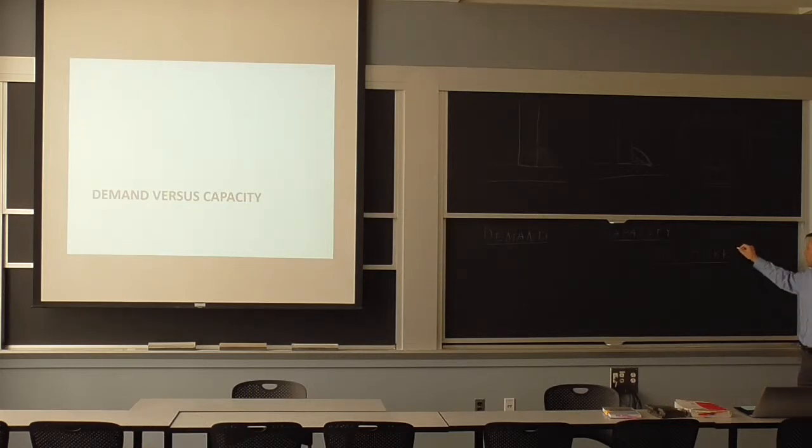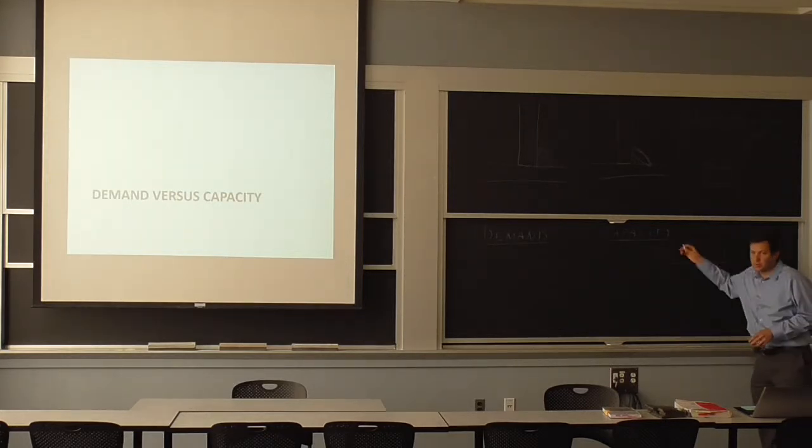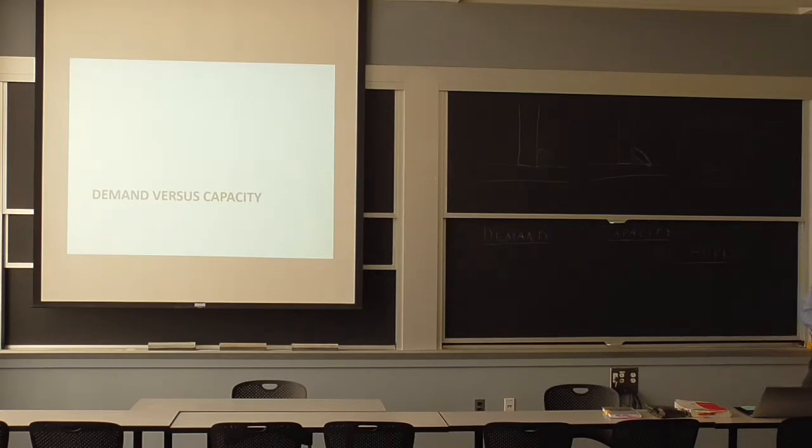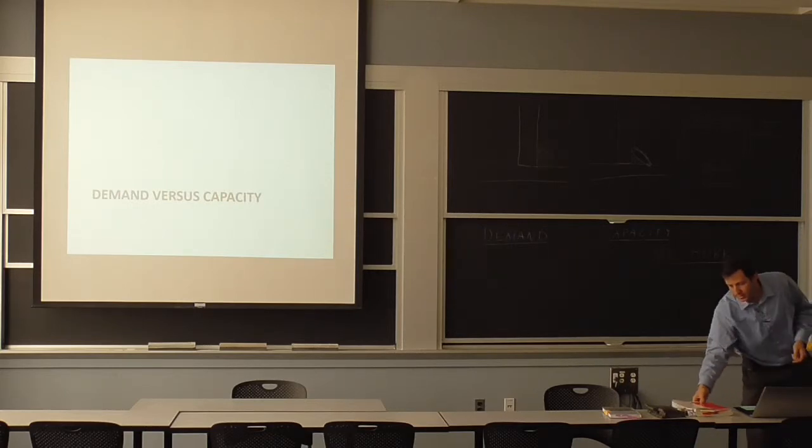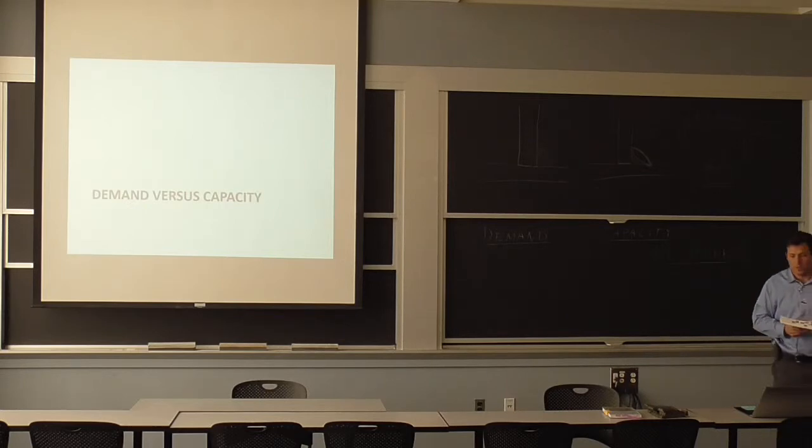There's a lot of qualification that goes into saying what will be the minimum capacity of this grade of alloy with these specifications. So you can use it after the fact. You don't have to do it yourself, even if you're making airframes for original jets or business jets. So it's a good source to say this is the minimum strength. AWS is another source. It will tell you, and we'll go through an example later, what the minimum strength is.